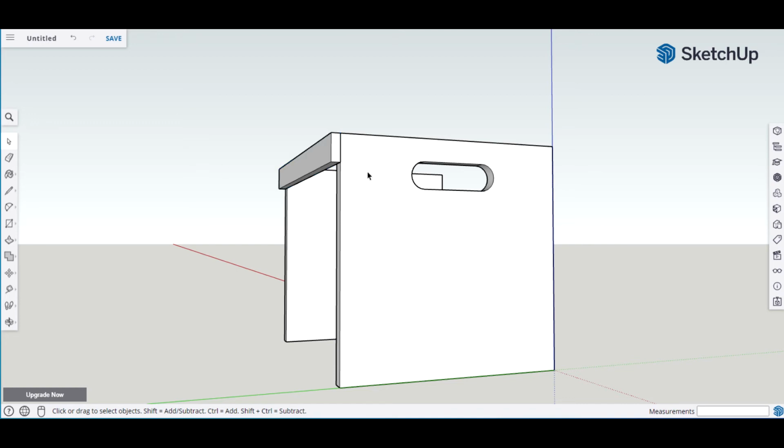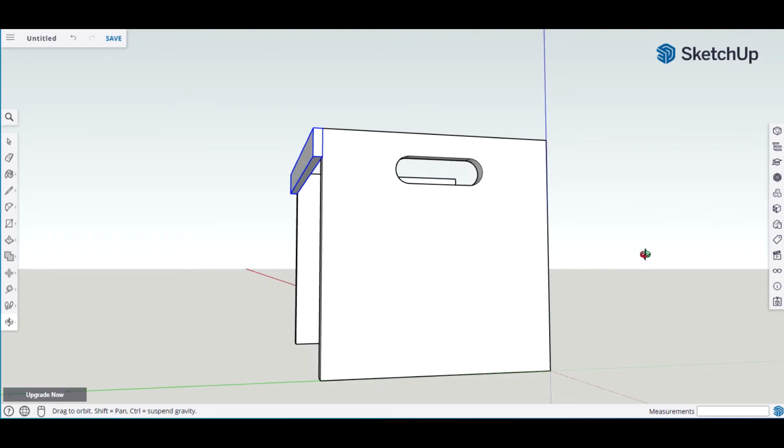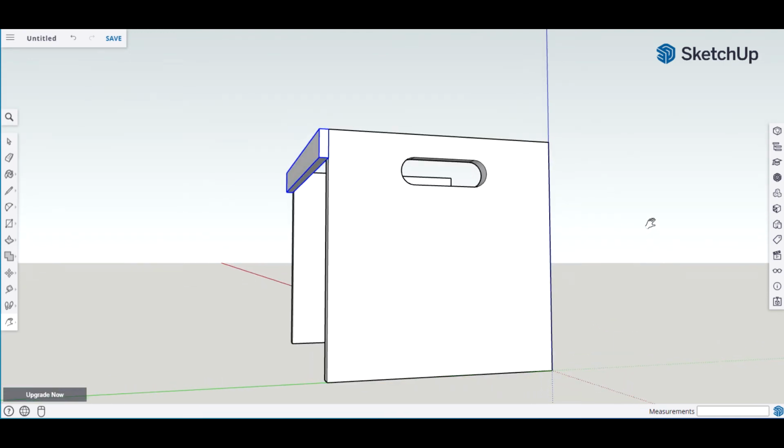We click free space, click it, and automatically clicks the whole slat. So click it again. Let me just pan this away a little bit. Let me bring this up a little bit here. All right. So let's select the slat, and we're going to attempt to select this corner here, so we can drop it down right here, and we can snap it into place. So we're going to move it and copy at the same time.